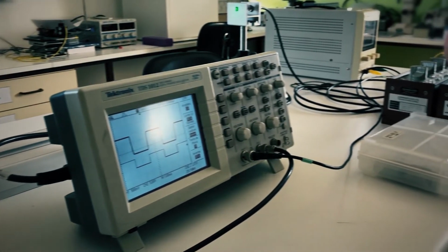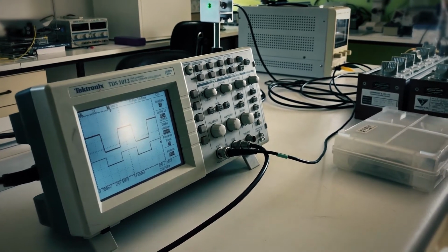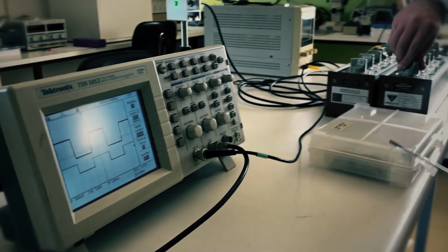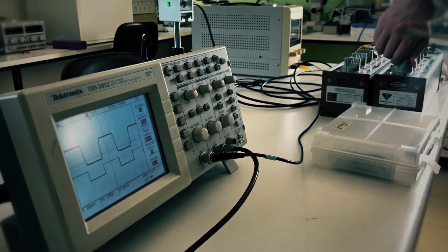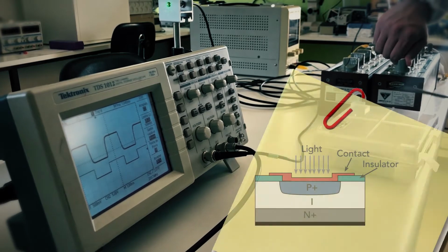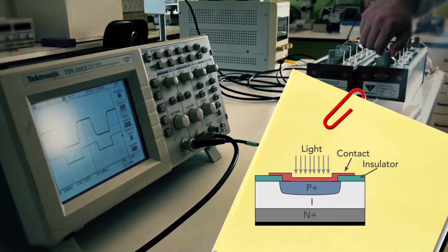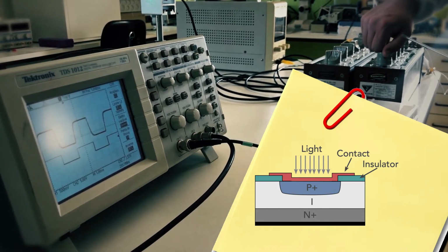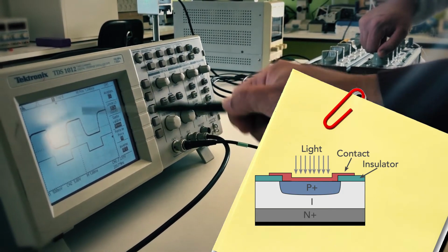Next, we aim to observe the effects of parasitic or junction capacitance. For this, we set the resistance value to about 200 ohms. To understand what we are about to simulate, let's take a look inside the photodiode. The outer layers are both doped semiconductors, and the middle layer is an intrinsic one. A not-so-conductive layer between two reasonably conductive layers acts as a capacitor.